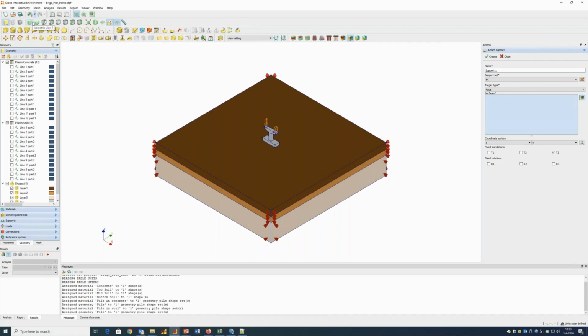So I think we are pretty complete now for the model. We have defined all the geometry part, the pile. We have assigned properties to the different part of the model. We have defined our deck load, and we have assigned boundary condition. So we can move to the mesh building part, which is the last stage before meshing. So here I want to assign some element size to the pier, and I go for 1 meter.